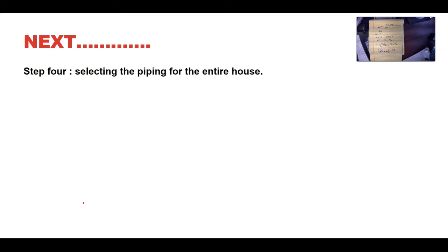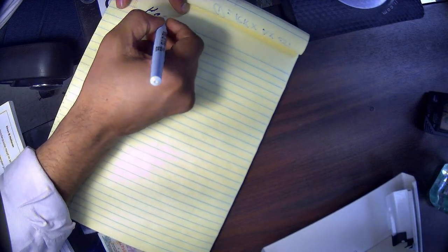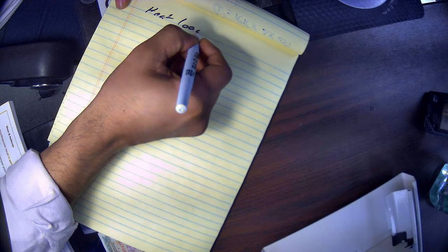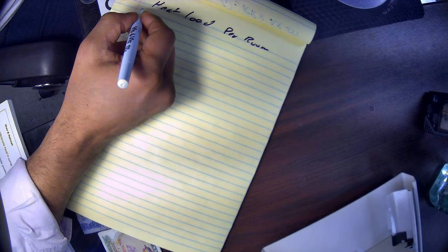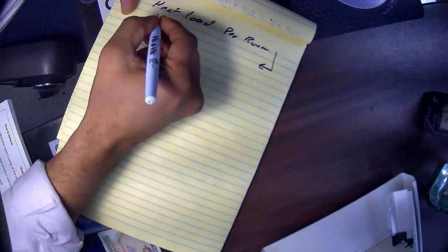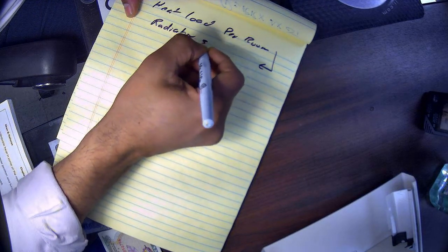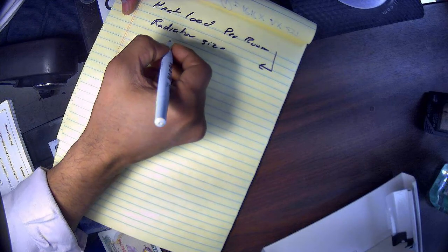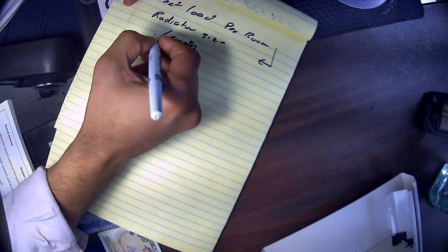So for now, what I want you to think of is, I'm going to make this a little bit bigger. So what you have to think about is heat load per room. Then this will go into radiator size. That's going to be length, right? If you're going to be using baseboard radiator, length of baseboard.